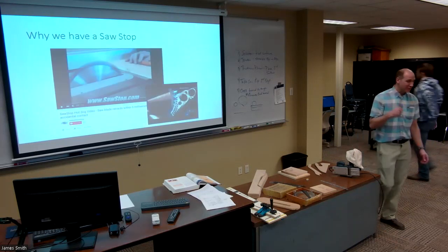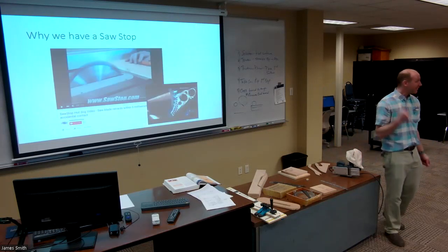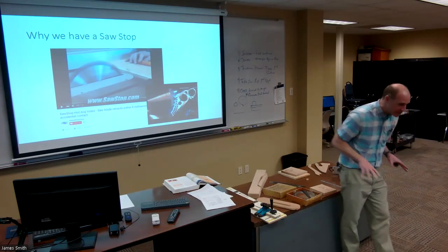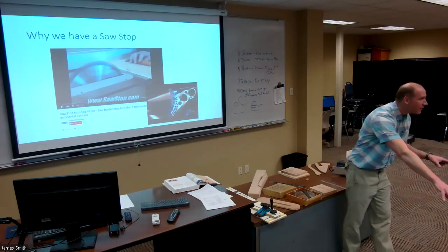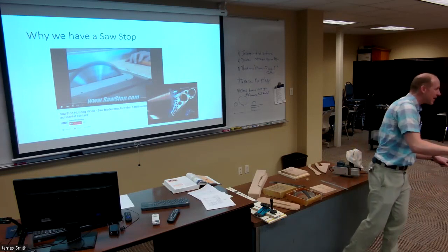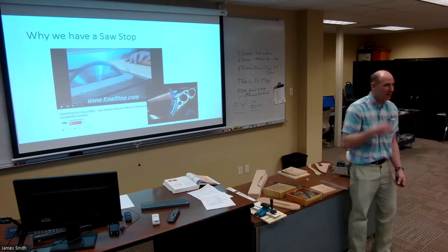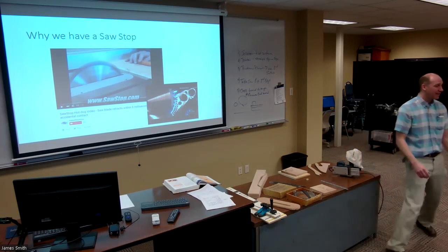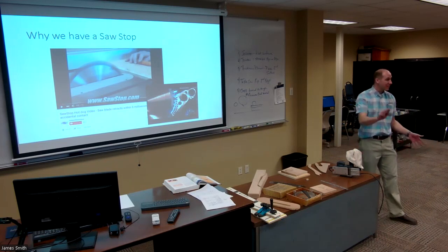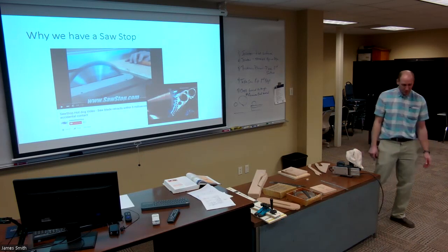We actually had a student who needed that. Local student, he was running his board through, got all the way through, and as he was reaching his hand over to grab the next piece, he nicked it with his finger. And I heard it, and bam, the thing happened like that. Moral of the story, don't get in a hurry. Don't reach over the blade. Be aware and be conscious of what you're doing at all times, and make sure you're well rested and you're focused.